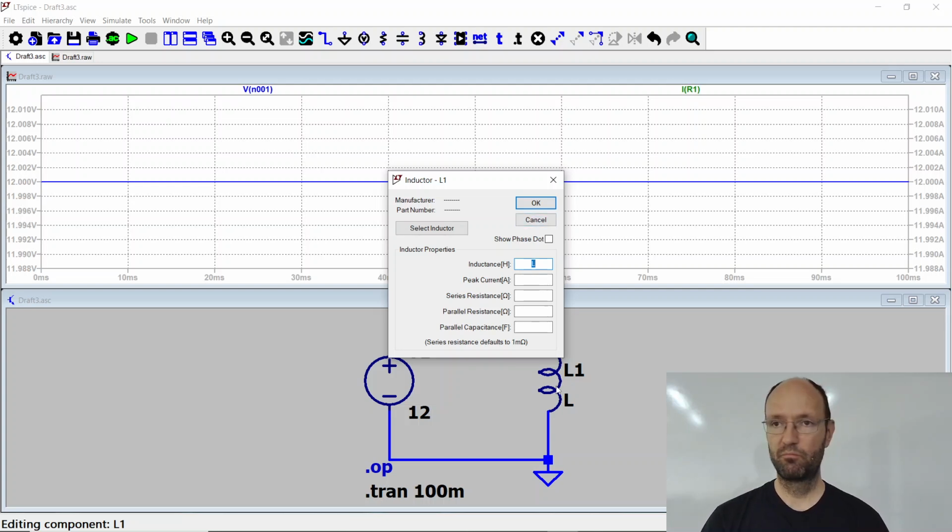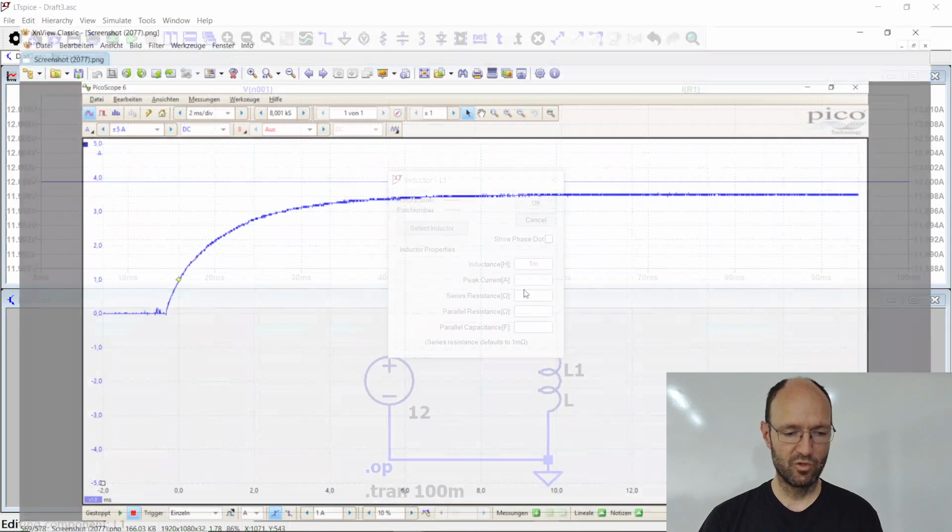Once again, if you click the alternative mouse button, the right mouse button on a right-hand mouse, we can set a value. And I would suggest to, for example, remember what we calculated on Wednesday approximately for the inductance of the motor, something like a millihenry, right? Because we had this time constant of 1 millisecond that we measured approximately. I have this diagram here open somewhere, right?